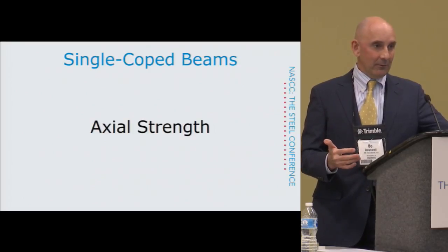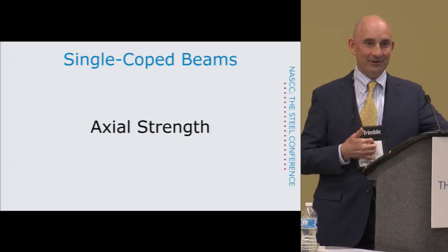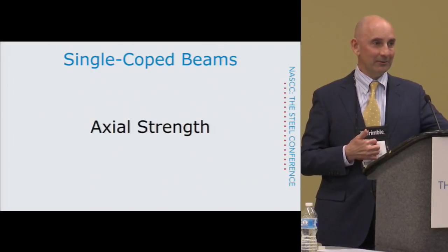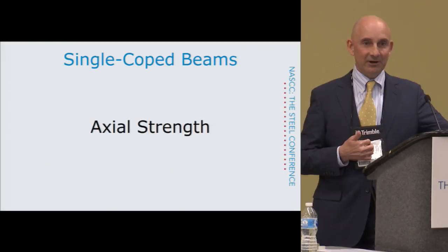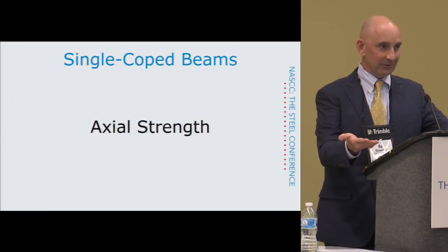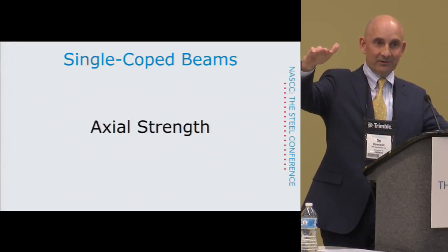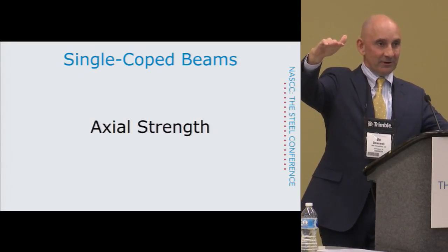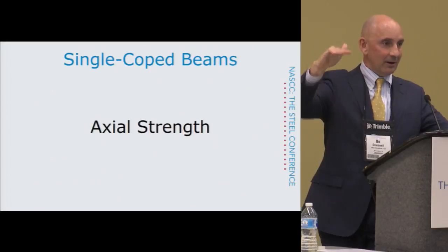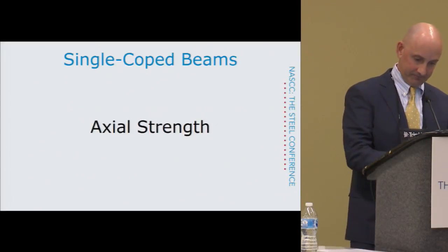We can all use our own judgment, but in my judgment, it's going to fail in a local buckling mode because that bottom flange is strong enough and stiff enough to brace the web at that location, and you'll get negligible deformation near that bottom flange, and all of your deformation, like a plate buckling problem, you would have near that top part where the flange is cut out.